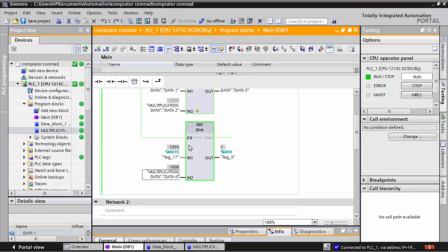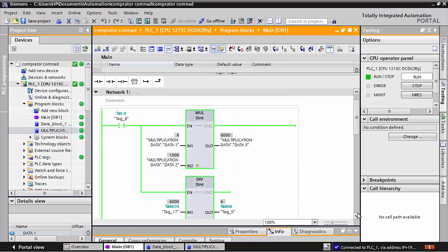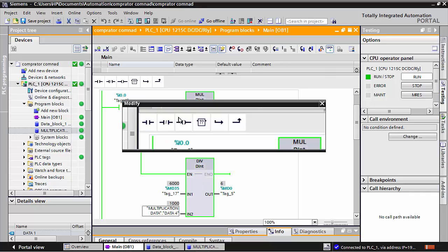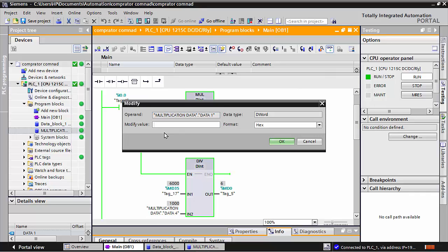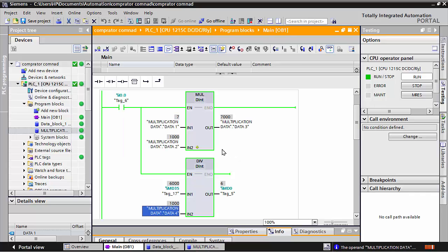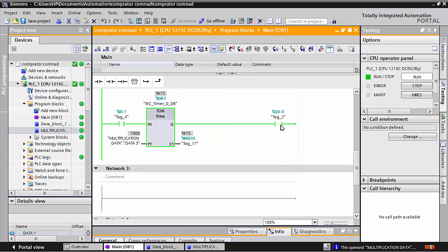When I start this one, after that you can see the display continuously in MD0. And if in this running time I change this data also, put 7, and as I stop and start the command again, you can see here your seconds will be running 4, 5, 6 and 7 seconds after our output will be executed.